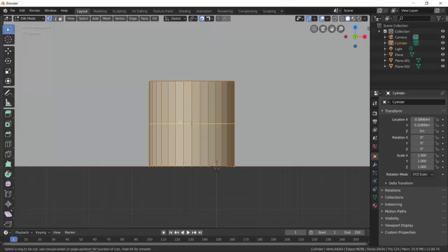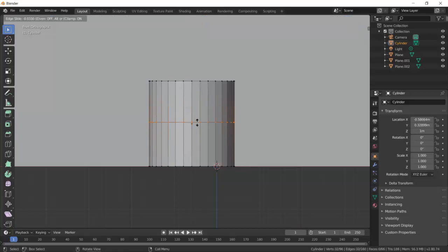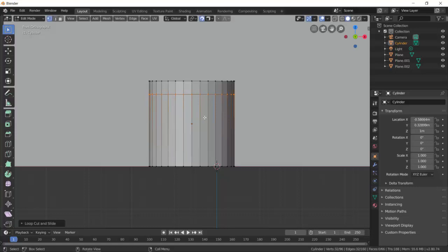Now you can do loop cuts on a vertical or on horizontal. So the first click is the plane that's going to do the cut in. So I click, and then if I just move it up and down, I can add several cuts. So I'm going to start with adding in a couple of different points. So I'm going to add in another one.